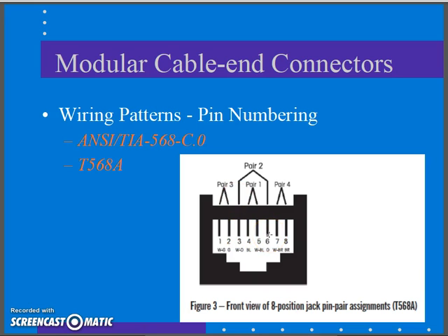It's in this arrangement so that I can actually plug a phone cable right here in the middle. I could plug an RJ11 in the middle of this outlet jack and have it work as a phone line. That's why this is a cabling standard that will support data and phone. So it looks weird that they're in the middle like that, but it's laid out that way on purpose because of phone. Then I see my pair 3 on the left and my pair 4 on the right.